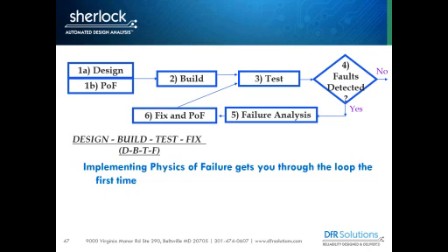That's why it's very necessary, and in fact you can still do it at the design phase, to understand what the field environment is, understand your qualification test stresses, and make sure those two are aligned so that any qual testing I'm doing matches the type of damage or loads I expect to see in the field. So we're doing design and POF at the same time. We build it. We're not eliminating test, and you're still going to have to show that this product is qualified and meets your requirements. But what we're doing is reducing the number of times you go through this loop.